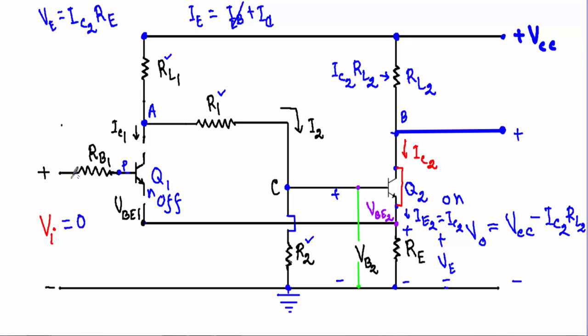That means if I want to turn on the transistor Q1 in normal mode, we have to apply a voltage greater than this base to emitter junction voltage, but here we have an additional voltage VE, which is also responsible to keep the base to emitter junction in reverse bias.